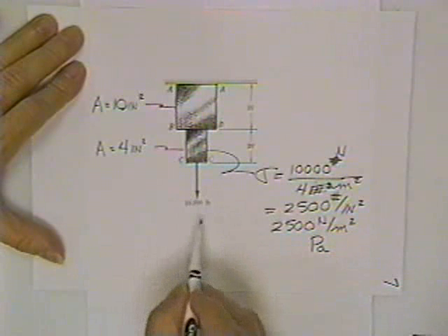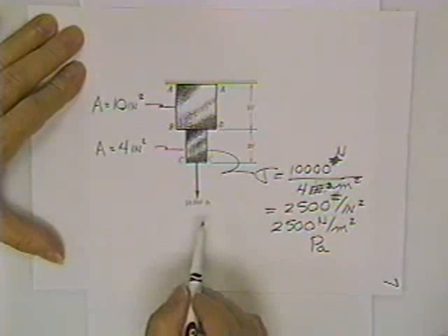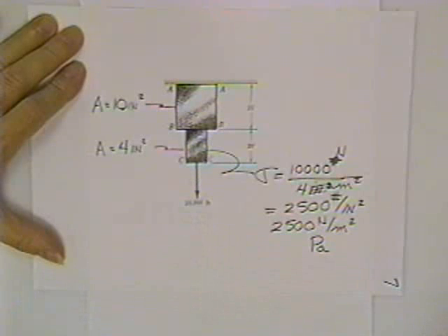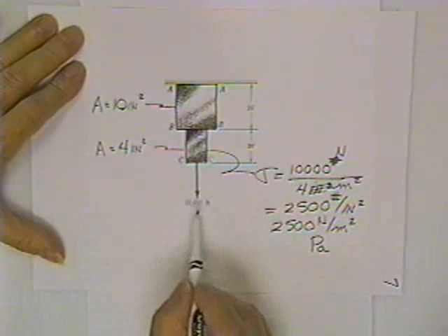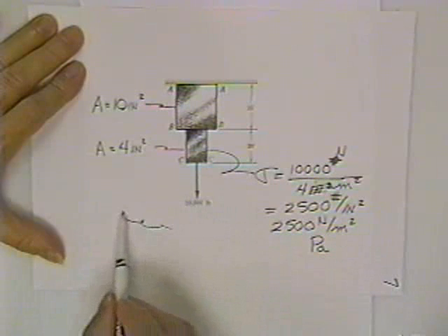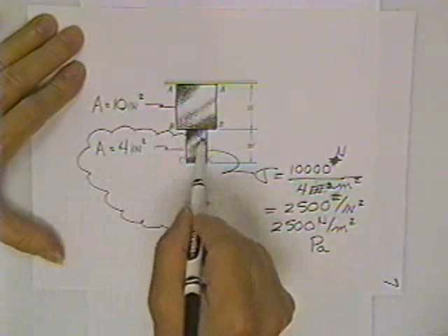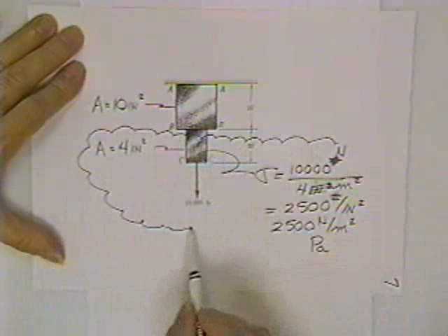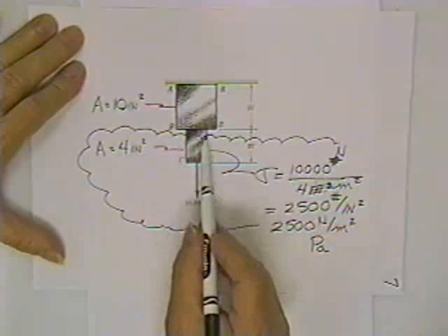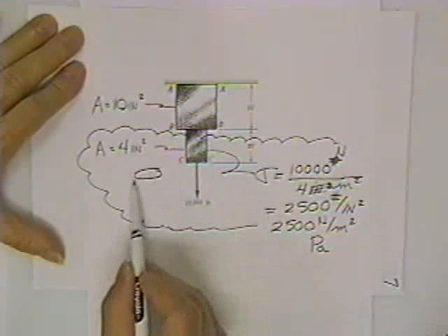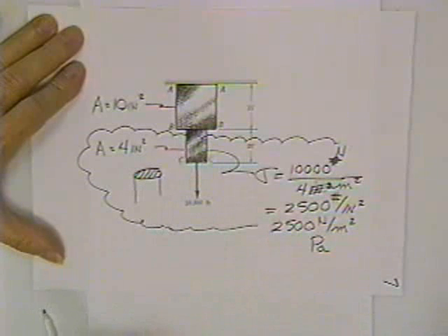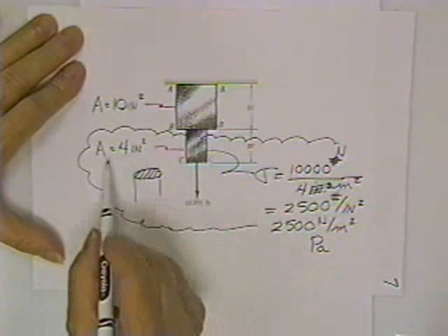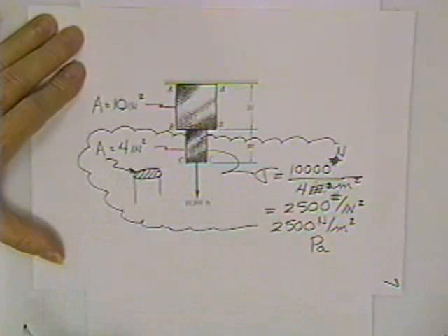The other day we did a review on statics, and the entire time was spent determining these loads. The way you get this load is you cut through the section that you'd like to analyze, and when you cut through that section, you expose what the thing looks like across its area, and that area we've been told is 4 square inches in this case.